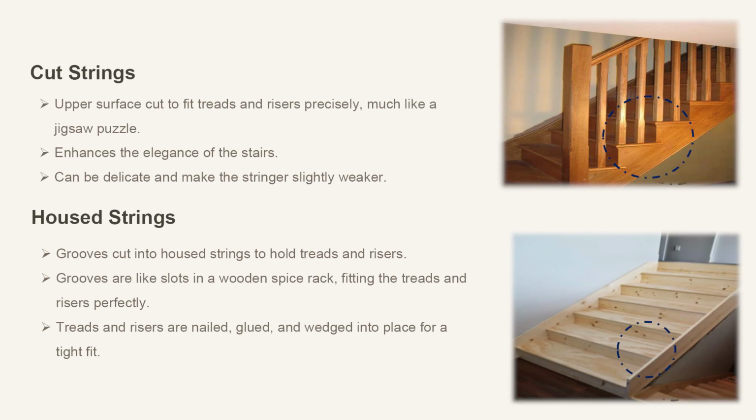First, cut strings. Cut strings have their upper surface cut to fit the tread and the riser precisely, much like how a jigsaw puzzle fits together. This makes the stairs look elegant, but just like jigsaw puzzle pieces, this can be delicate and these cuts make the stringers a bit weaker.